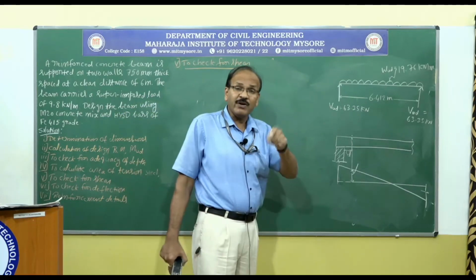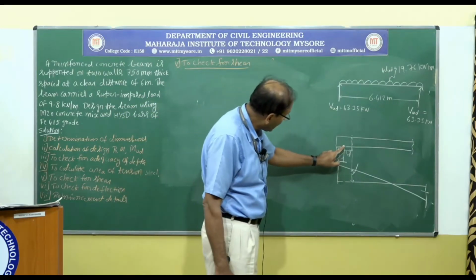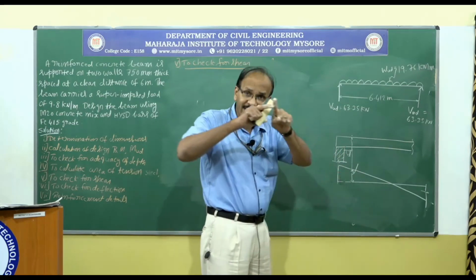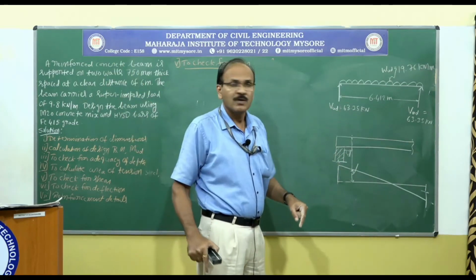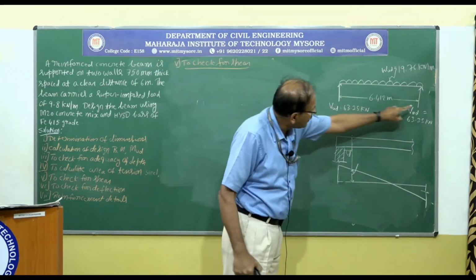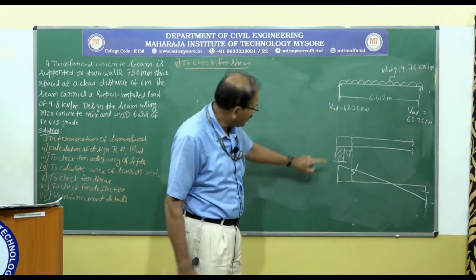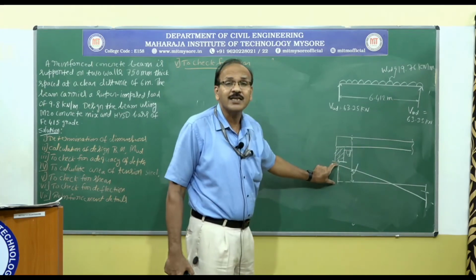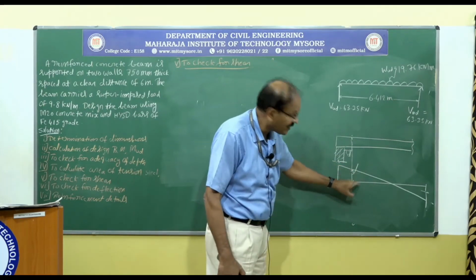Again, to further simplify, instead of taking the clear span, what I have done is I have taken the effective span, which comes somewhere here. Again, that shear is going to be more than the shear here and here.